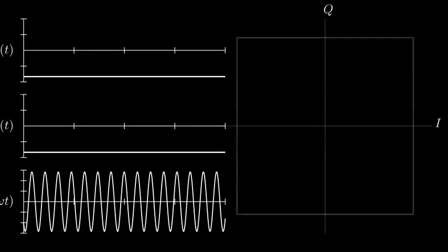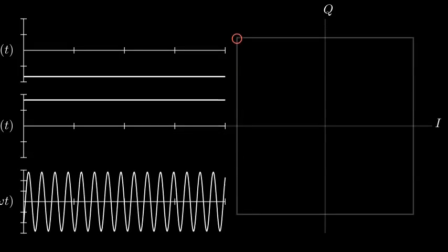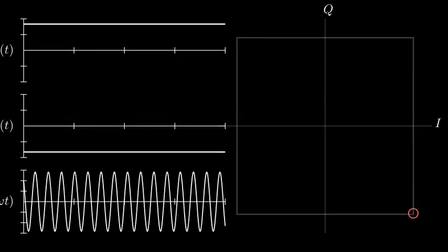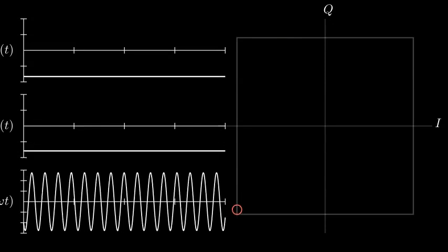So the benefit of quadrature amplitude modulation, as you can see in the visualization, is that we can send more information per wave packet, and we can even do more than 4 different locations. We can do like 16 or 256 if we change how many levels I and Q can occupy. So that's quadrature amplitude modulation and amplitude modulation and the basics of them. I was going to try to do a quadrature amplitude modulation transmitter build, but that would have been a bit more money and I'm lazy.